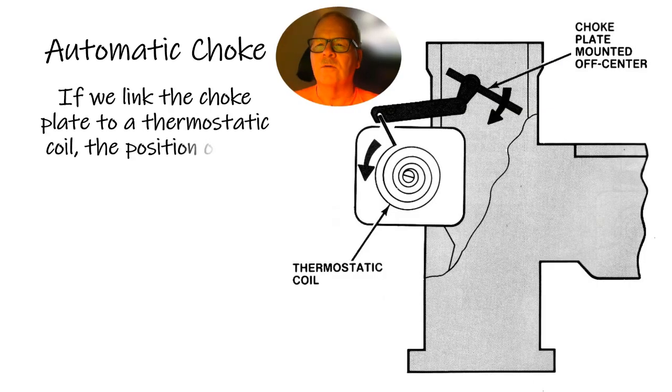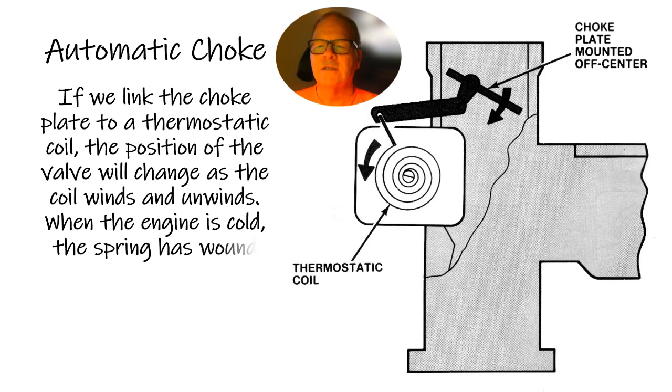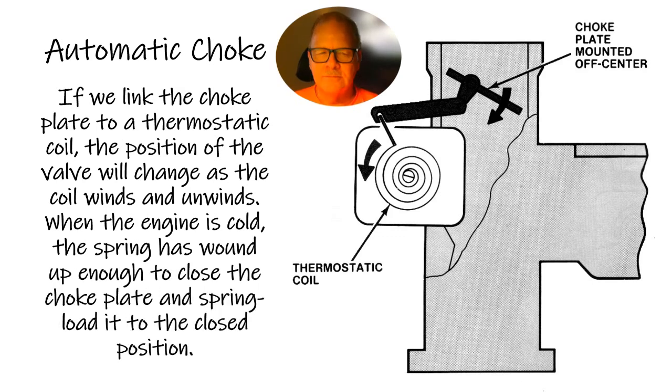All right, so now you've got this automatic choke. To start with, we had to pull it, like on your lawnmower, we had to pull the choke. And then as it started, we want to close that choke just as quick as we can. If you leave the choke pulled out, it thins the oil, because gasoline from that rich mix goes by the rings and gets in the oil.